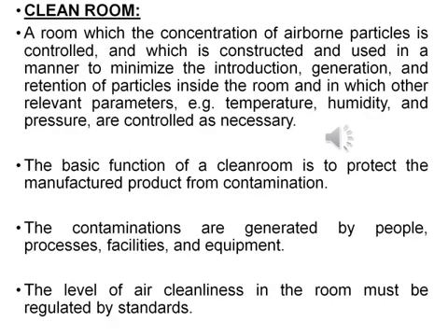Clean room. A room in which the concentration of airborne particles is controlled and which is constructed and used in a manner to minimize the introduction, generation, and retention of particles inside the room, and in which other relevant parameters such as temperature, humidity, and pressure are controlled as necessary. The basic function of a clean room is to protect the manufactured product from contamination. The contaminants are generated by people, processes, facilities, and equipment. The level of air cleanliness in the room must be regulated by standards.